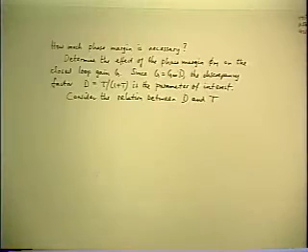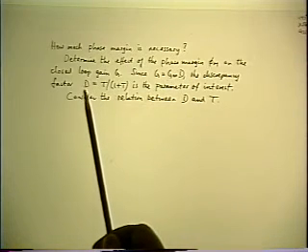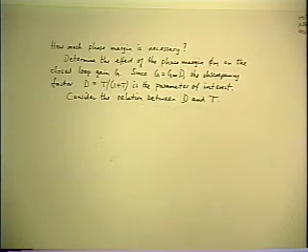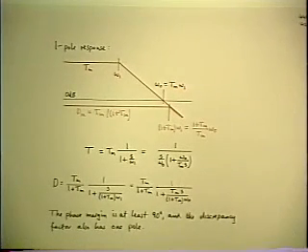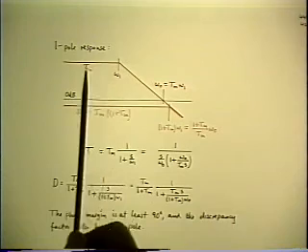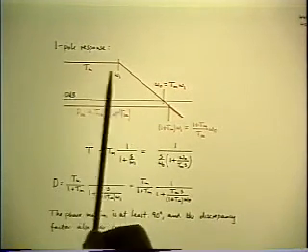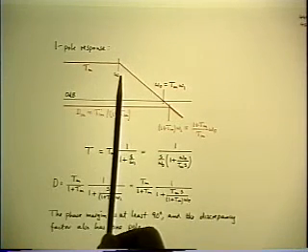So let's go back to the first part of the answer, which you can answer in general, because of a unique relationship between phase margin and discrepancy factor. Since it's unique, we can say something about it in the general case. So let's start working on that. Let's start, as usual, with the simplest case: a single pole loop gain, Tm flat value, pole at omega 1.